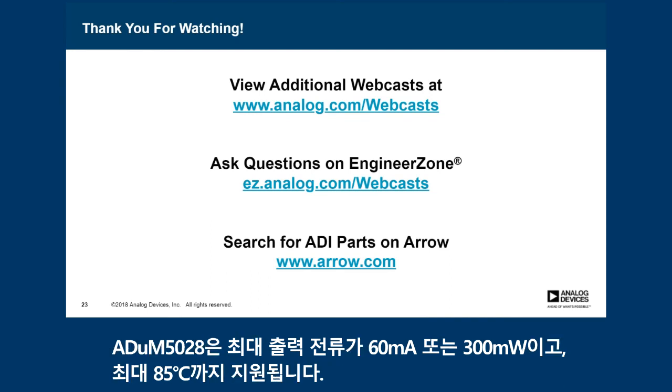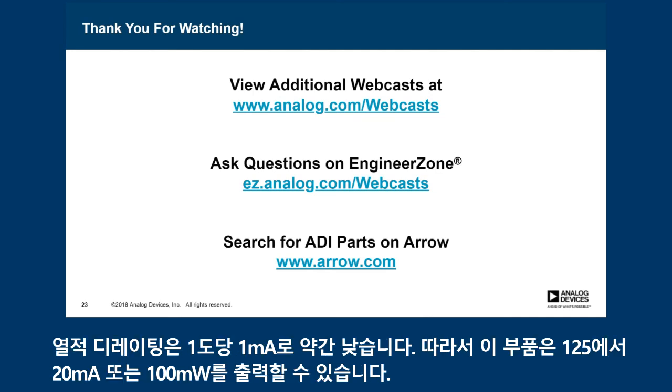The ADuM5028 has a maximum output current of 60 milliamps or 300 milliwatts up to 85 C. The thermal derating is a little bit lower at 1 milliamp per degree, so that at 125, that part is capable of producing 20 milliamps or 100 milliwatts.